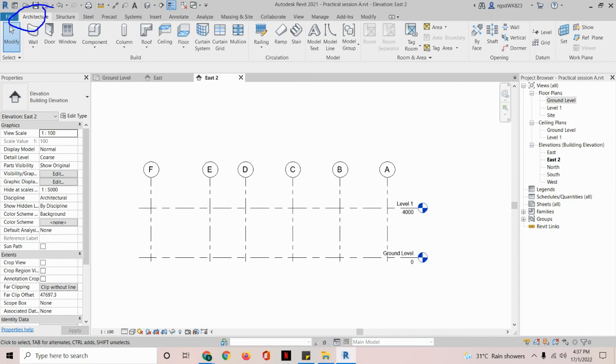You click on this, and you'll notice that on our datum here, the level is enabled, meaning we are only able to put in levels in this elevation view. So always check where our view is. If you are on this elevation view, this marker will be enabled and we are able to add more levels onto our drawing area.